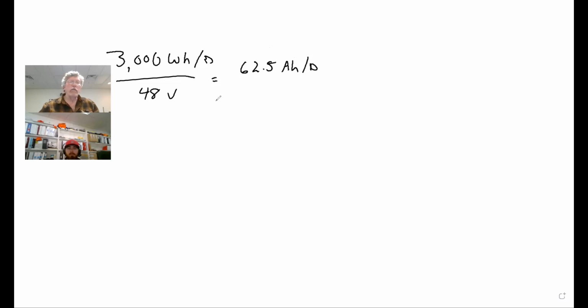Well, we were told we wanted 2 days of autonomy. So I've got 2 days. So that's going to be, what's that, 125? Yep. So I need a system that's 125 amp hours. Now, it told me that my entire system was derated at 75%, but my inverter was 95%.